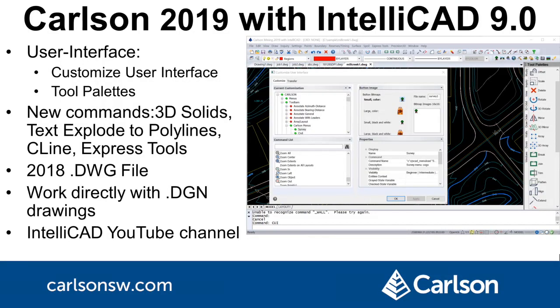IntelliCAD 9 has a new Customize User Interface command for workspaces and menus and to easily customize toolbars. For example, to add a command to the toolbar, simply drag and drop the command from the list onto the toolbar. Also, there's a new Tool Palette interface. New commands include a set of facet modeler functions for 3D solids, text explode to polylines, construction line, and several